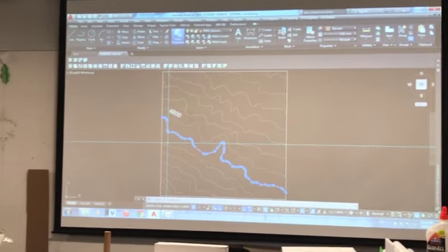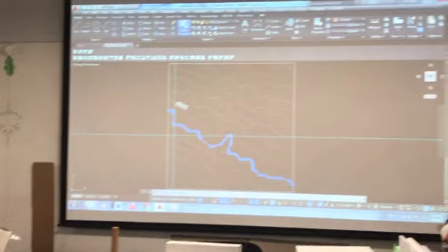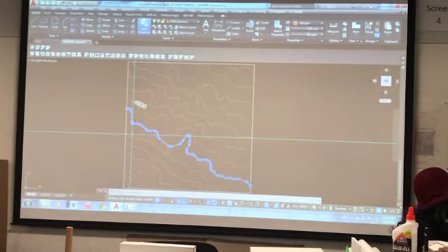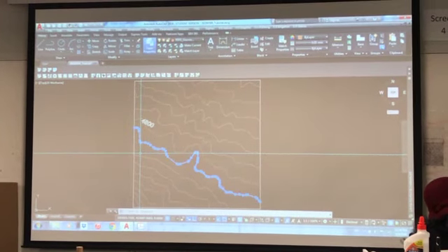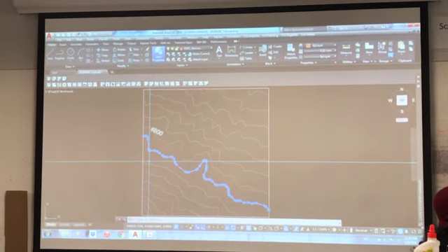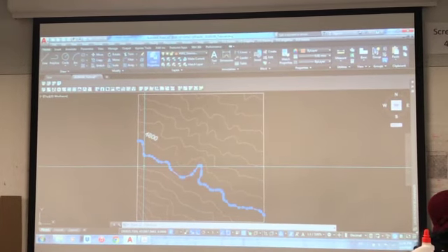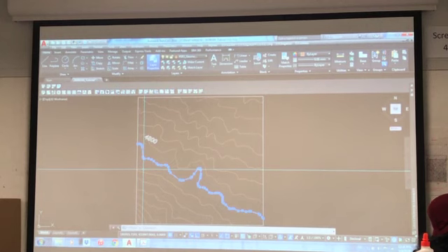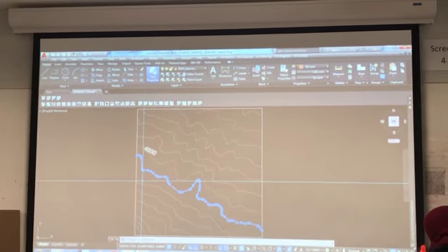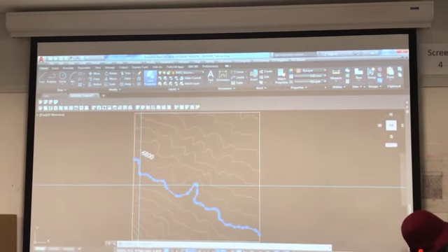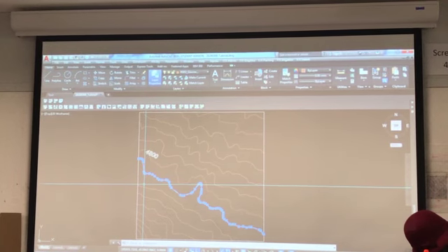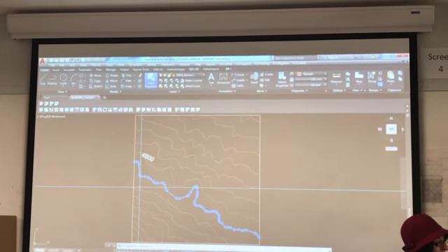Now, again, one of the hardest things that we were debugging out of students' projects last term, I think two common errors are that you create and cut your contours and do them backwards, and you mistake the low for high. Another one is when you have a closed figure like the one Kevin's referring to, sometimes it's hard to know whether that's a valley, a depression, or a peak.